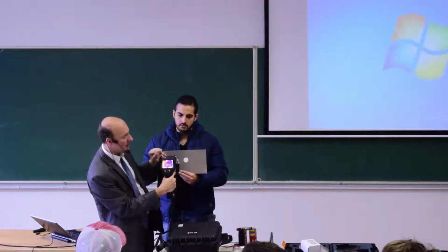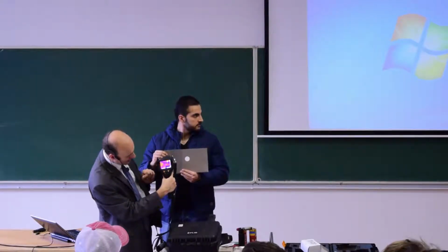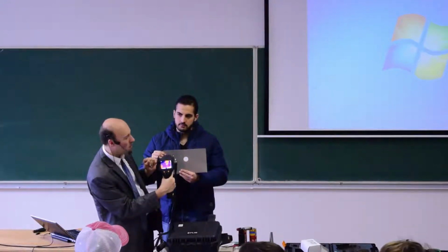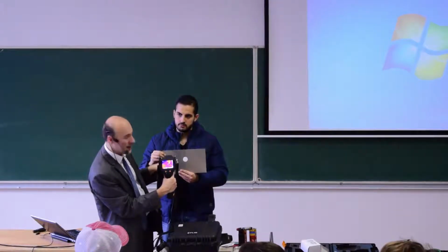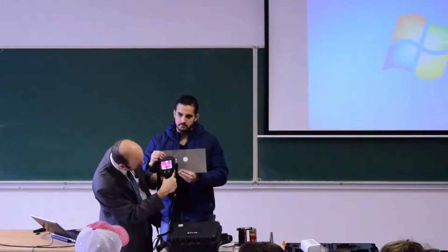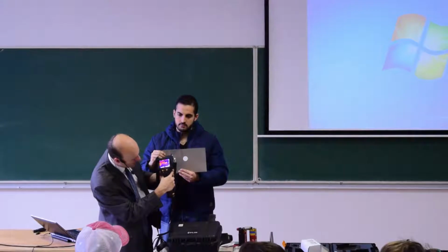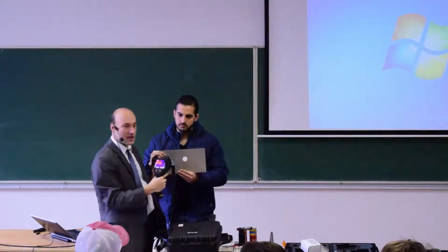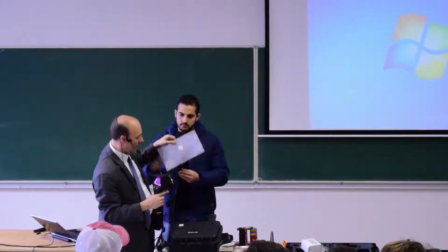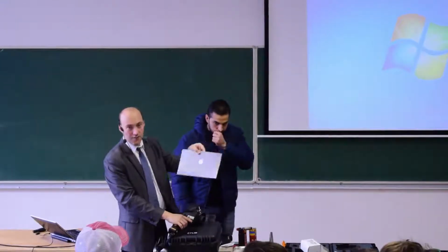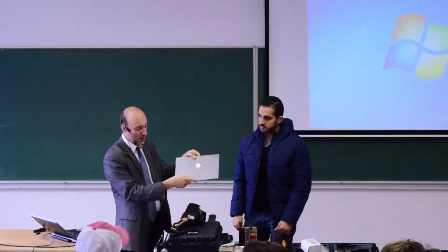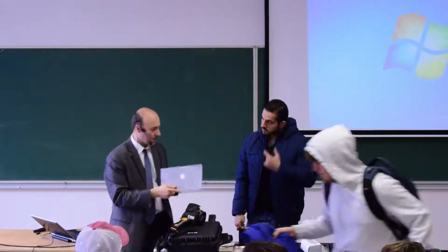This sticker has a defined emissivity. In this case, it's 0.96. And now I can read that on the sticker, it's showing me 25 centigrade. That's because here I have defined the emissivity of my object, and now I am able to read the temperature.